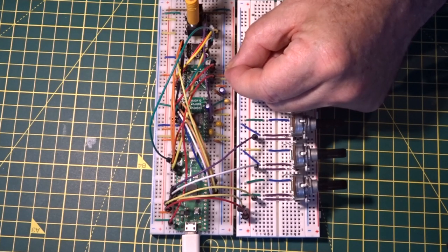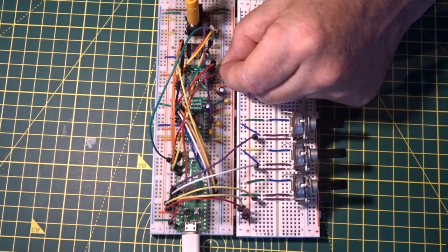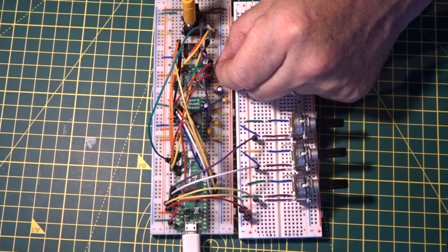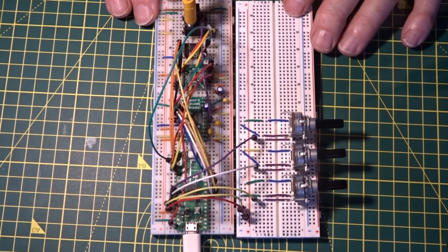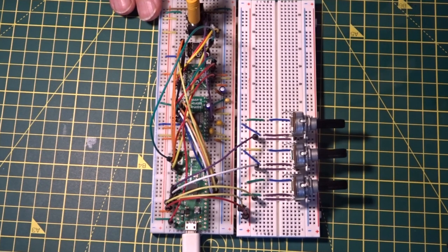If I put a capacitor across the input here, that's across the 5-volt line, ordinarily you'd expect that to smooth the line out, but it makes it far worse. So I think I've got noise, and we're going to have to do something about that. And it's probably that I'm trying to run high-speed audio on a breadboard, and breadboards are horrendous when it comes to, you know, decent ground planes or anything like that.